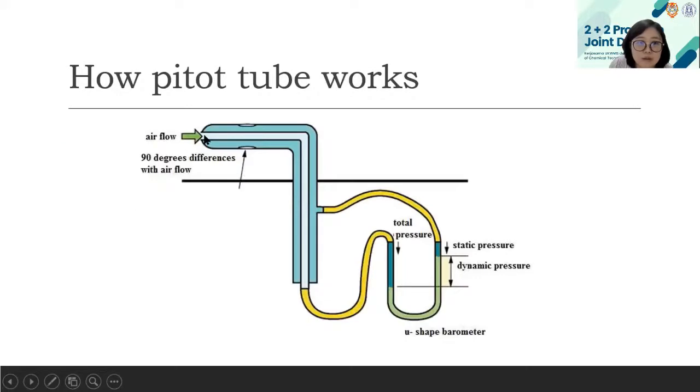If you put it near the wall, then it will only check the flow rate near the wall. If you put it a little higher, near the middle part of the pipe, then the Pitot tube will only measure at those exact points. It will not check your total average velocity.